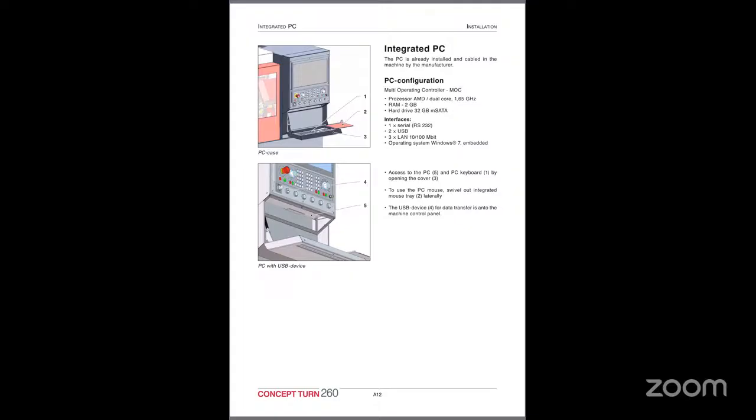An initial inspection is required before turning on the machine. Check the chuck, coolant level, lubrication oil, air pressure, emergency stop, door lock, and turret.